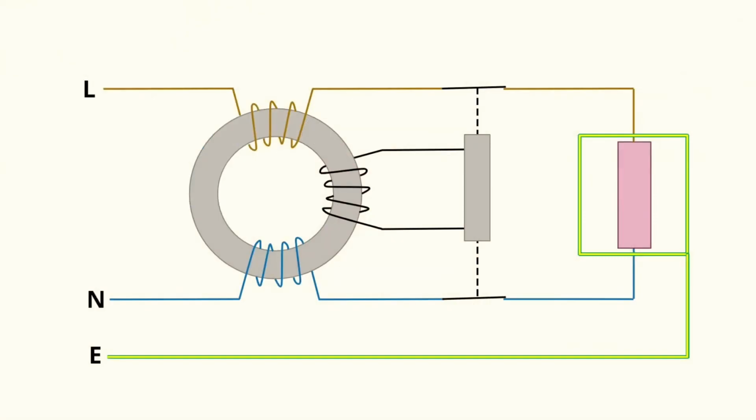Why not? Well, to answer that, let's look in a little more depth at how an RCD operates. Now, we've got a diagram here you can see of a traditional RCD, what's referred to as an AC type RCD, which is the basic RCD that we've mostly been installing for years and years. Inside the RCD, the line conductor wraps around this toroidal or ring-shaped piece of soft iron. It then goes off and feeds the load.